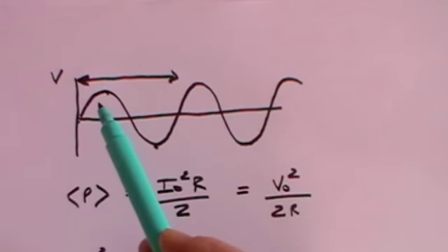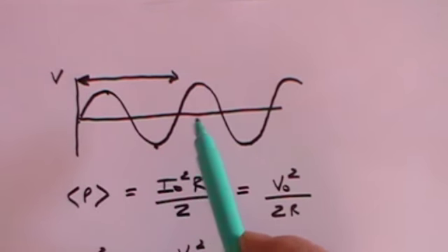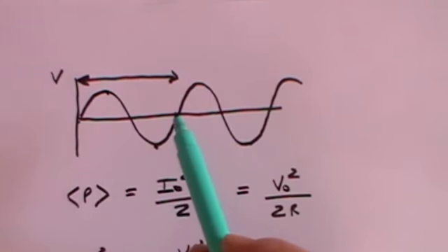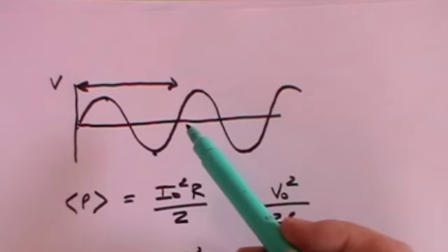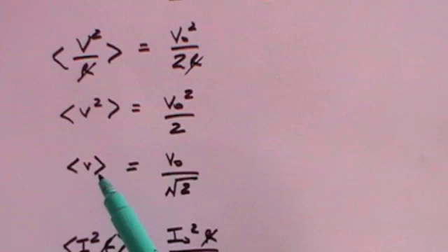the average voltage is that, of course, the voltage coming out of the wall is always giving you some power, and that power is the equivalent of this voltage. We derived it from the power term. So it's the voltage that effectively gives you that power. If instead of having a variable voltage, you had that as a direct current voltage, then it would produce the same amount of power. So we need to understand that.